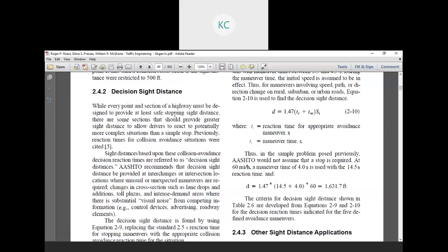It is recommended for a particular highway or class of highway, like the national highway or state highway, but in that particular vicinity, a greater sight clearance or safe stopping sight distance is required, like at the intersection, because there are a high number of merging and diverging lanes available.